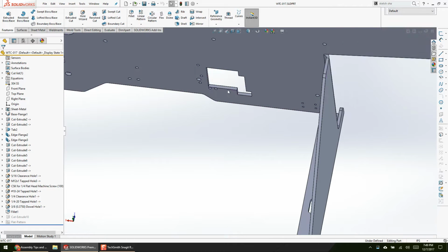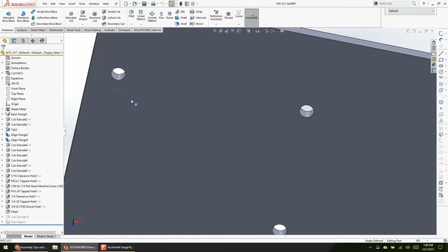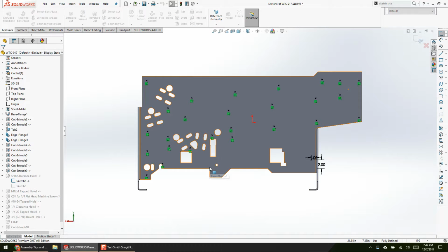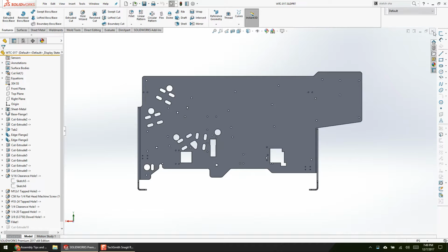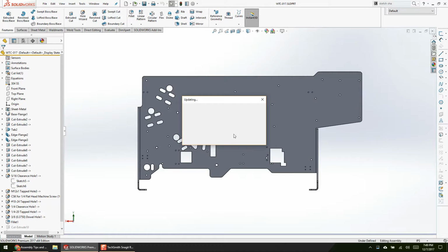And I think it's here. Been a while since I've been in this design, so I don't necessarily know it. Yeah, so those are just pseudo-randomly spaced holes, right? And a lot of people think they're really smart using copy with mates and then click, click, click, click, click. And you get an instance of the component and 2 or 3 mates copied multiple times.